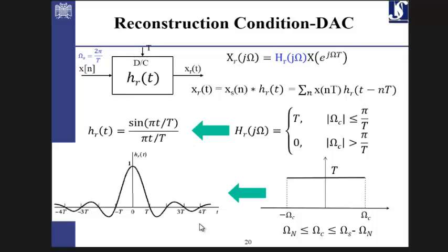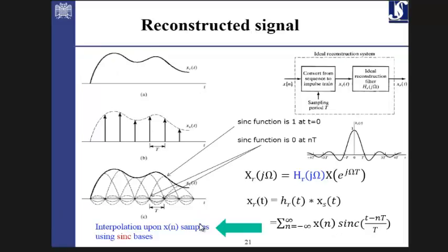So this sinc function, we know that every sinc function goes from minus infinity to plus infinity. Is it possible to have this convolution in time for the signal with something that goes from minus infinity to plus infinity, and then you're shifting that sinc function again and again, and you need to go back to the continuous time signal? Of course it's not possible.